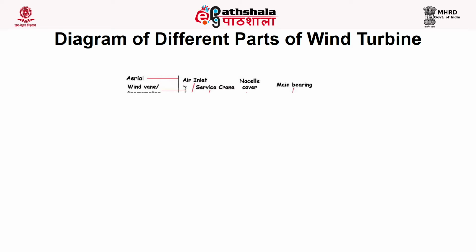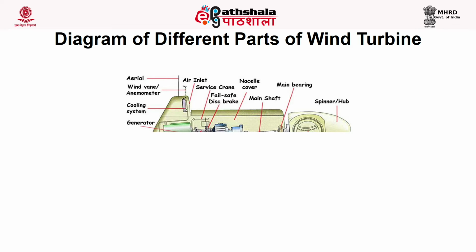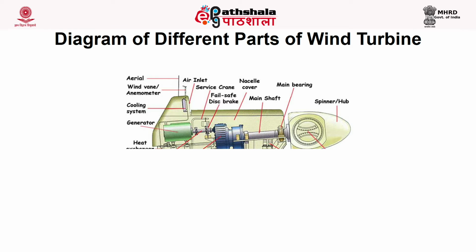For the rotor, there are two types, which are the horizontal axis and the vertical axis rotor. The vertical axis machines operate in all wind directions and there is no need of yaw adjustment. The windmill head or turbine consists of the rotor and the housing of the rotor bearings. It houses control mechanisms incorporated, like changing the pitch of the blades, safety devices, and a tail vane to orient the rotor to face the wind.